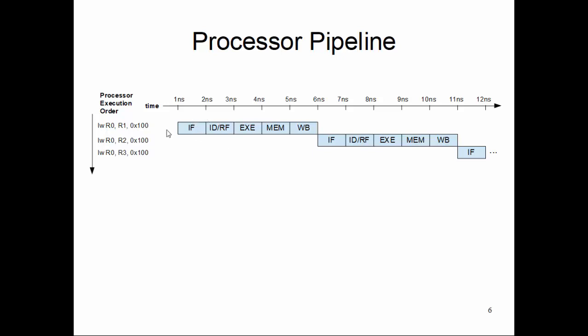So essentially one instruction takes 5 clock cycles to be completed. Once one instruction is done, then we go with the next instruction: instruction fetch, decode, execute, memory, and write back, and then the next instruction goes. That is the way our processor works, and any basic processor does it that way.